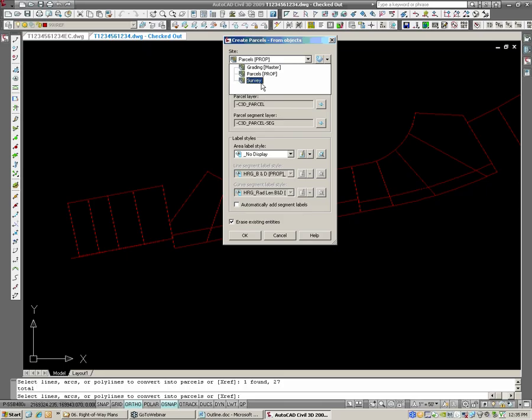When survey is creating existing parcels, they should make a parcels existing site, just like there's a parcels proposed, to put the parcels in their own separate site, or the survey figures start to interfere with the parcels. That's a different thing. But for our parcels proposed here, we're going to choose this parcel proposed, and that's just an empty site, just a shell. Just trying to get the workflow moving in the right direction for people. I know it's a little different here.